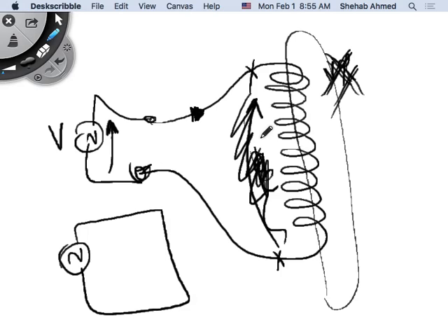If you try to put a DC source across a transformer, you will saturate the core. You will increase flux in one polarity, and that's it. You will not have the time varying flux. If you don't have the time varying flux, you don't have a back EMF voltage developed. You basically have a short circuit across the transformer.